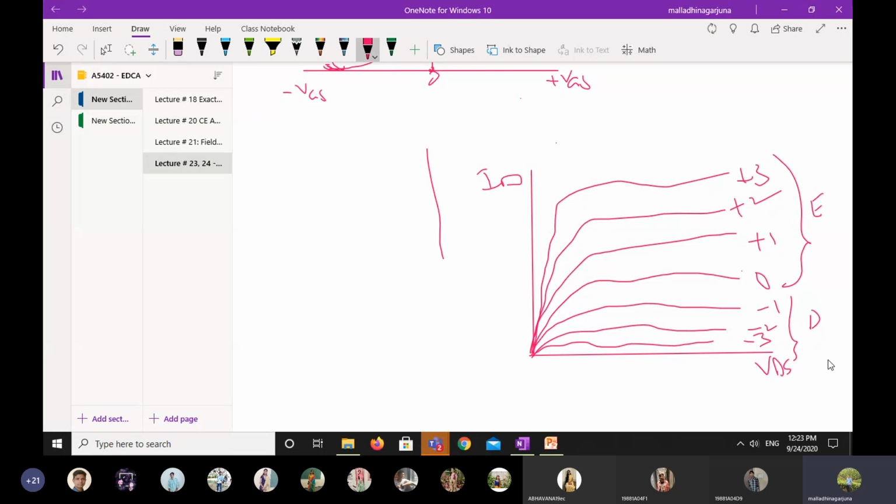If there is no need of allotting some area for the channel, the area can be saved and the size of the transistor will be less, very narrow. Whereas in the depletion MOSFET, a channel is available in the structure, so it occupies more area. Comparing with E MOSFET, D MOSFET occupies more area.